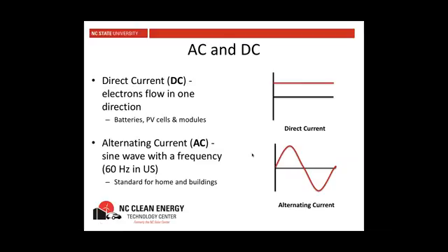with the electricity that comes out of a battery or out of a PV module, which is always DC. There are a lot of different options for how and where we convert it, but we have to make that direct current into alternating current to be able to feed it back into our houses and into the electricity grid. We'll talk a little more about AC and DC later in the class, but mainly you just have to be aware that PV modules and batteries produce DC. In our houses, we're using AC. Everything being supplied by the utility grid around the world is alternating current.